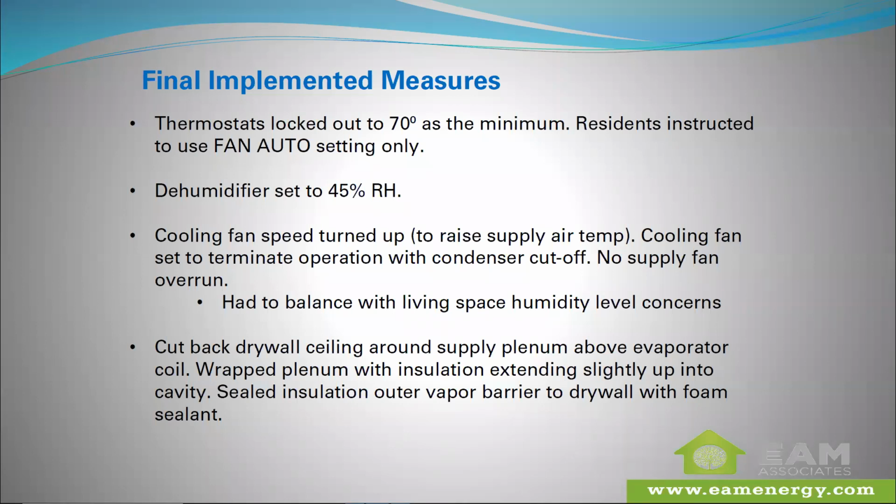In this case, we actually wanted to deliver slightly warmer supply air because we wanted the ducts to stop getting so cold. Now we had to balance that though, because you could take that too far and then start having humidity issues with your actual indoor air quality. So that's a balance that has to be struck.